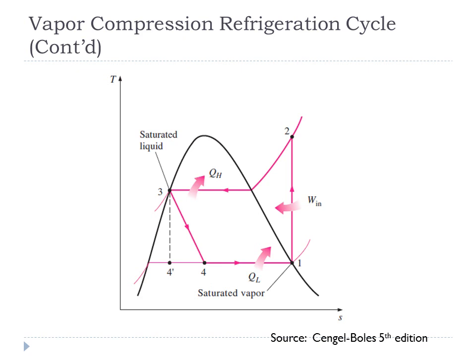We can see that this compression process which was carried out inside the compressor is represented here by 1 to 2 line, which is an isentropic line, because on x-axis we have entropy S and on y-axis we have temperature T, and we can see how temperature is increasing during this compression process.